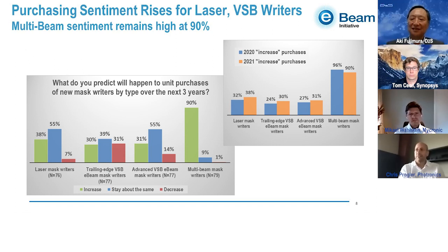You know, in the early days of IMS, when I was actually on their board for a while, and then they were acquired, as you guys know, I really pushed to try to have a really high-speed, mid-range multi-beam mask writer. Something that can knock out a 28 nanometer, 40 nanometer node mask in an hour and a half. It would be a very different tool than what we have today. I'm totally speculating here, but I'm sure they'd be selling as many or more of those today than they are of the cutting edge multi-beam tool, if it was commercially available.